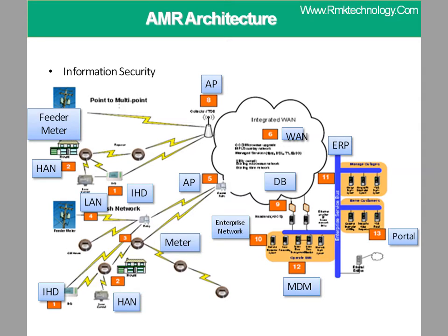This slide depicts various communication channels used in smart metering solution. Field devices are connected to dedicated networks through wired or wireless communication. Radio meters are connected to remote data collectors which collect all the parameters coming from meters as telegrams. Telegram is the parameters that are set in meters which need to be transferred to application systems. These include values like different types of readings like kWh, kVAh, kW, meter temperature, battery life etc.